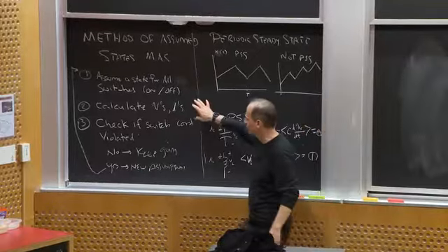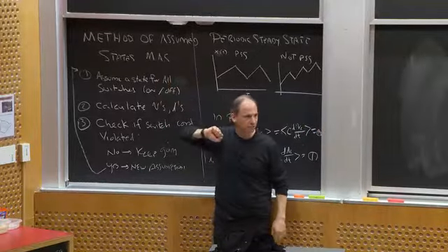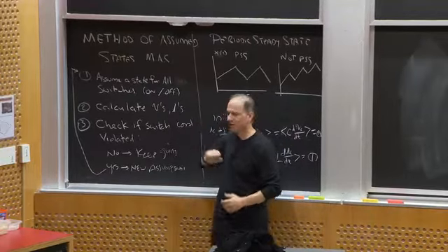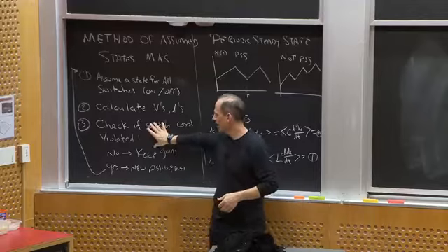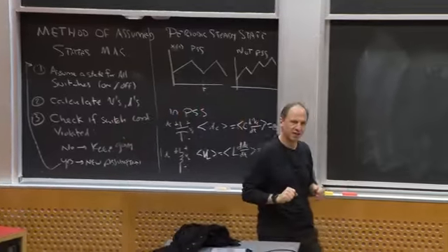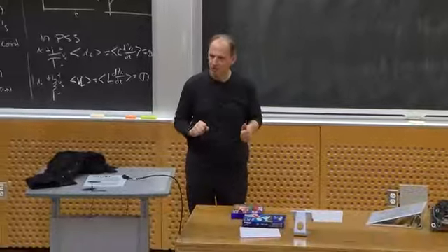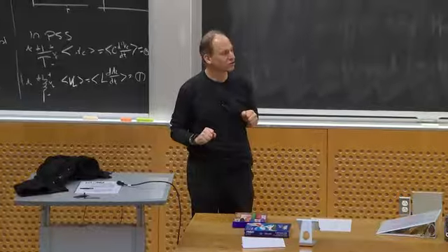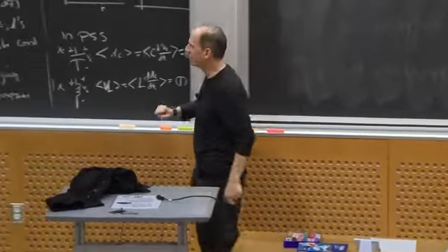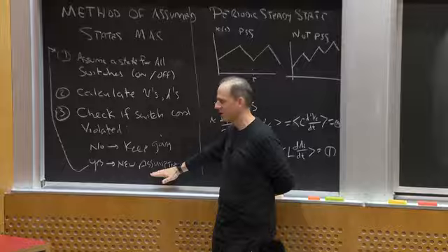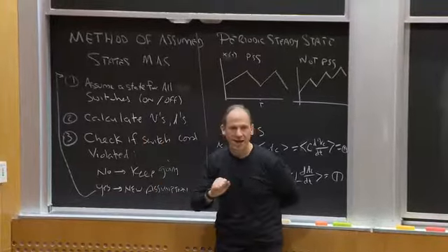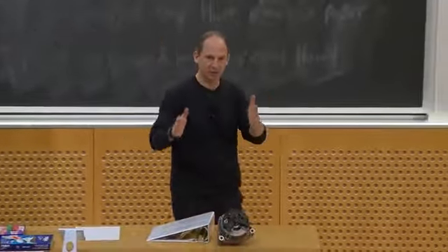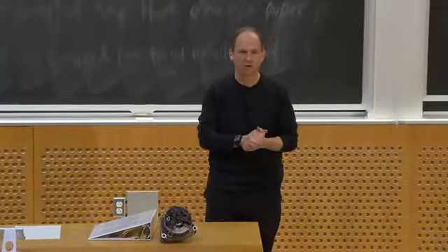Essentially, we take a guess, maybe an educated guess, and set up the diode states to be on or off and replace them by open or short circuits. Then we calculate the voltages and currents in the circuits. Then we check if the switch conditions are violated. That is, does a diode have a forward positive voltage when I think it's off, which we know it can't? Or does it have a negative current when it's on, which we know it can't? If one of those switch conditions is violated, it's time to make a new assumption. Otherwise, we were happy with the state and we keep going. We work this through time to figure out what's happening as devices are turning on and off over some switching cycle.